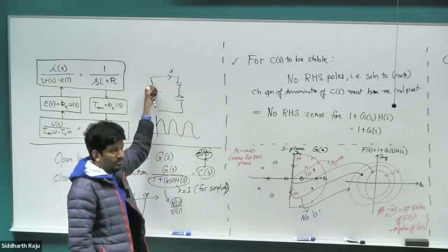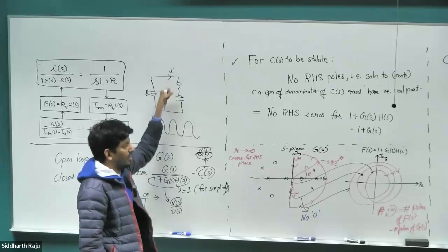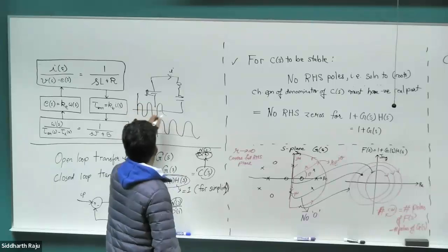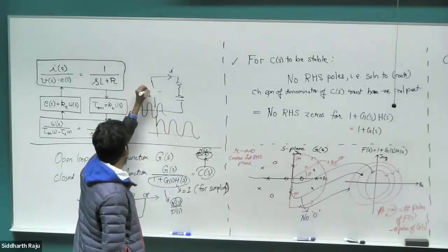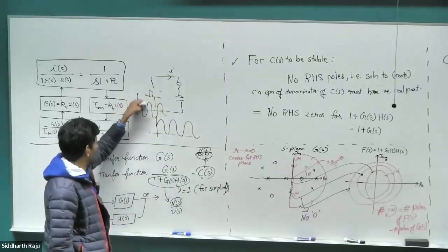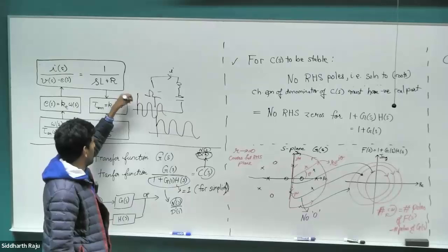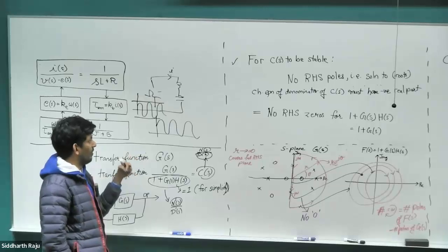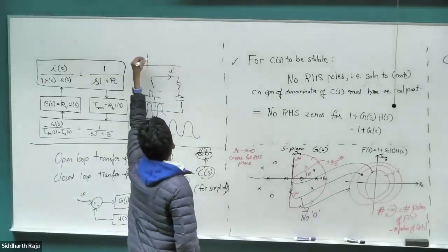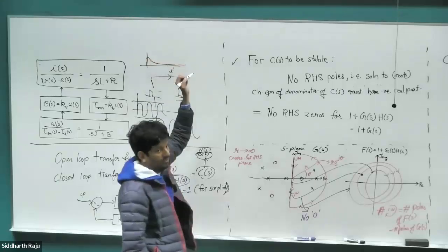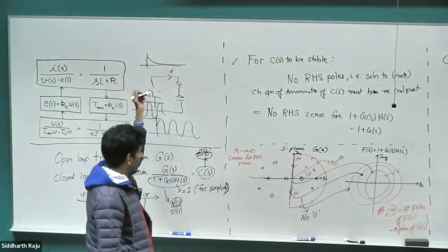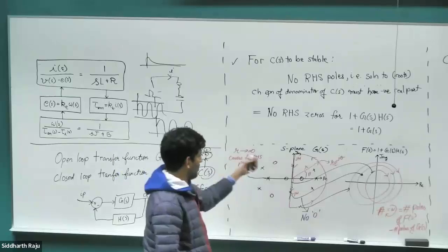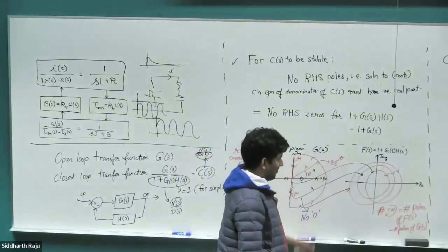If you give an impulse voltage, a tiny amount of voltage, and short this out, this is basically a tank circuit, right? The energy is going to oscillate between the capacitor, inductor, capacitor, inductor. So the current for that, if you give an impulse voltage, would look like this, right? So instead of a DC voltage, I give a pulse and then turn it off. There is going to be a current which goes on and off, right? It is bounded. There is an upper limit and a lower limit for the signal. So it satisfies one condition for stability, but it doesn't satisfy the other condition for strict stability, which is that for an impulse input you would expect an output that would converge to zero, right? So it doesn't satisfy that. Whether you want to call it stable or unstable is totally up to you, but it's not strictly stable, but it's stable, right? So that's what would happen if you had poles on the imaginary axis.